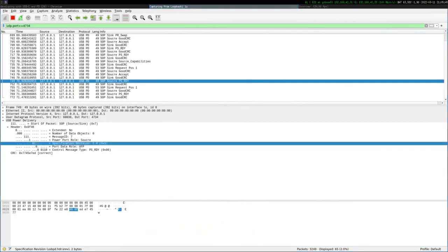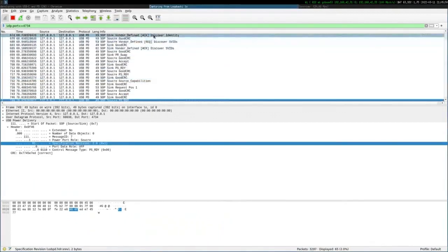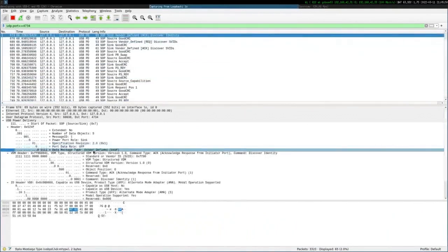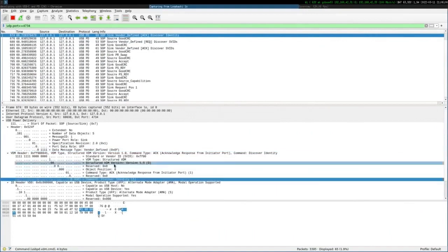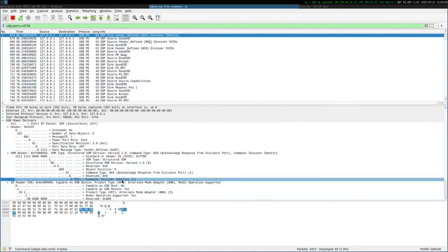You can encapsulate absolutely custom messages in PD using vendor-defined messages. This is actually what we have in the Discover Identity. The Discover Identity is a vendor-defined message. This one is a Discover Identity command. You can have proprietary messages. You even have firmware upgrade over power delivery, which allows you to upgrade the cable, or to upgrade any device which is not really a device which connects using a cable, but a device called a VPD, a Vconn powered device. So it acts just as a plug of a cable and not as a complete device.